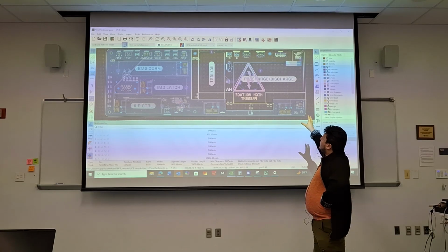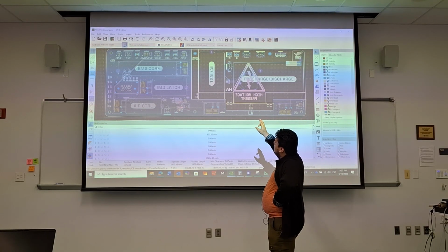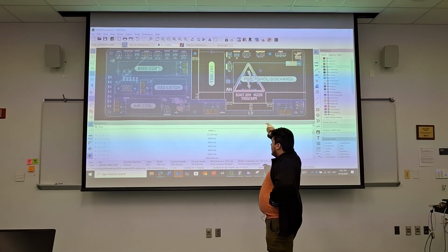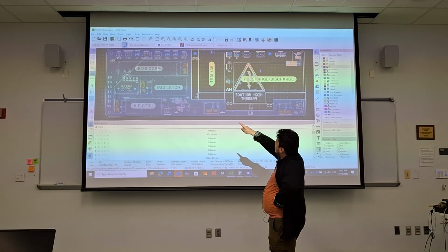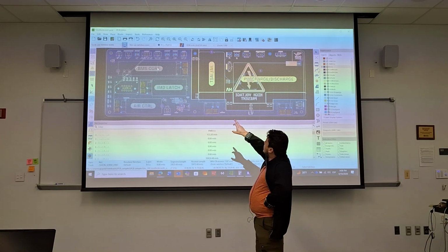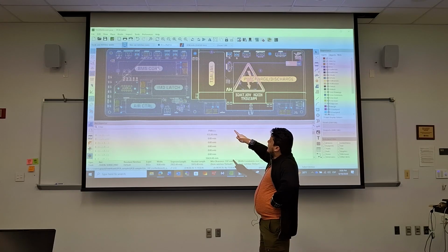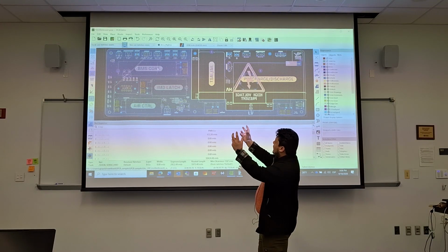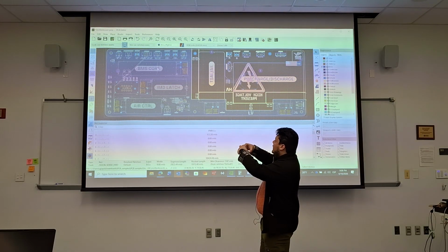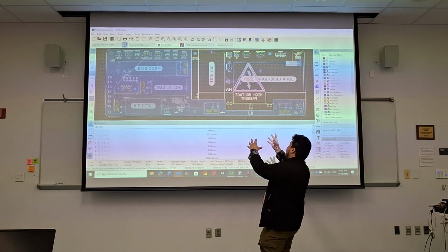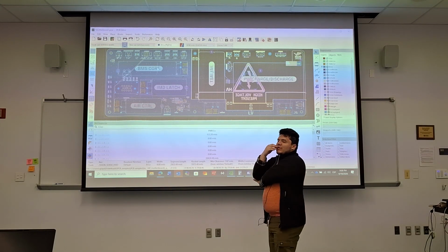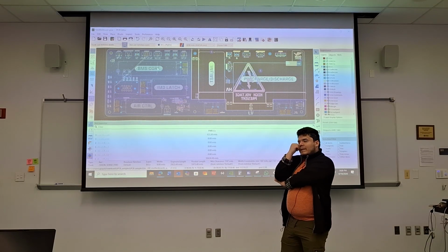Either that second reference or, another thing I'm looking at, I'm just not sure it's grounded right because you have 3 different boards connecting to one big board. You're assuming that they all have the same ground, but that's not necessarily true because they have their internal local references, but then you're expecting that to reference. It might be fine. You just have to double check your grounding scheme.